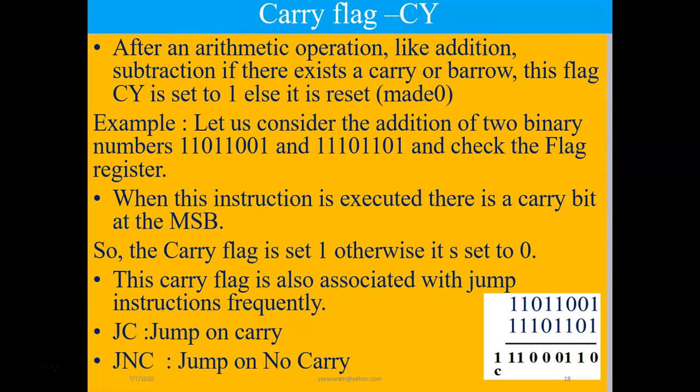So as you know, another most important, which is very, very popular, is the carry flag or carry bit. What is this carry bit? Whenever you perform an arithmetic operation on two numbers, if there is a carry from the MSB to the next bit, when this instruction is executed, there is a carry bit at the MSB. Then the carry bit will be set.